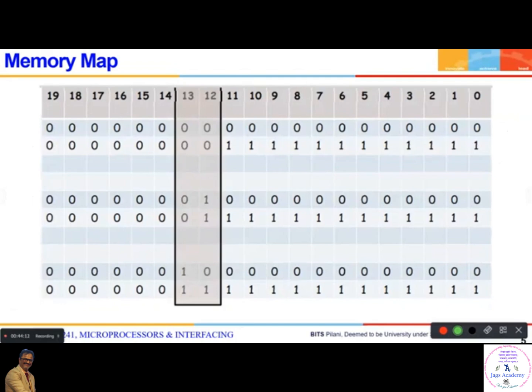2K requires 11 address lines, but 4K requires 12. So now there is a mismatch. What you can do is select your A0 as even and odd as usual. The remaining lines will go to the chip address lines directly. Then whatever remains after the address lines, you take as decoder select inputs. And if you still have any address lines remaining, take them as enable inputs to the decoder.